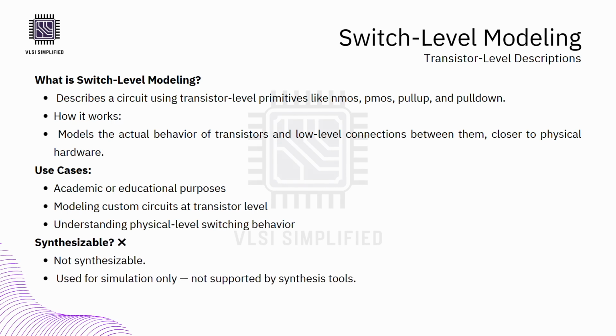Let's begin with the lowest abstraction level, switch level. In switch level modeling, we describe a circuit using individual transistors. Verilog provides primitive elements like NMOS and PMOS to model how real hardware behaves at the transistor level. This type of modeling is very close to physical design. It's like describing every wire and switch on a microscopic scale.